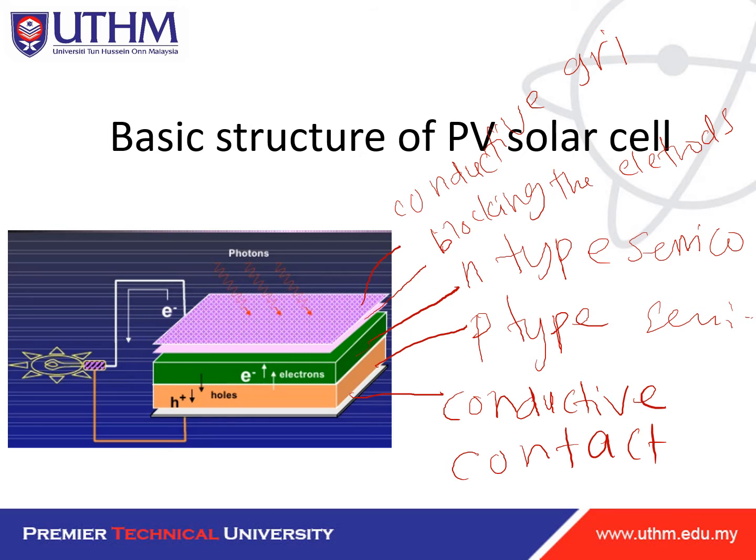In a PV cell, the absorbed photon energy generates electron-hole pairs that become a source of electricity. Electrons flow to the positive side of the load and holes flow to the negative side of the load. Then, in a PN junction solar cell, a bulk potential is the major driving force. The difference in work function of two contacts could be another driving force in charge separation.